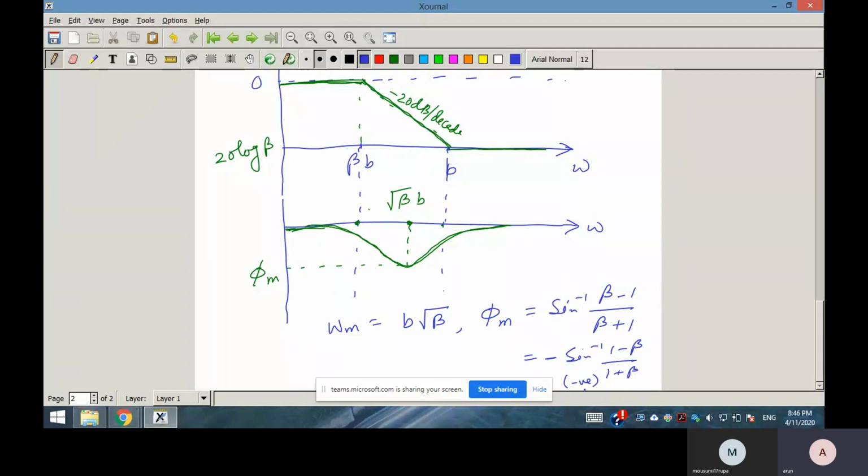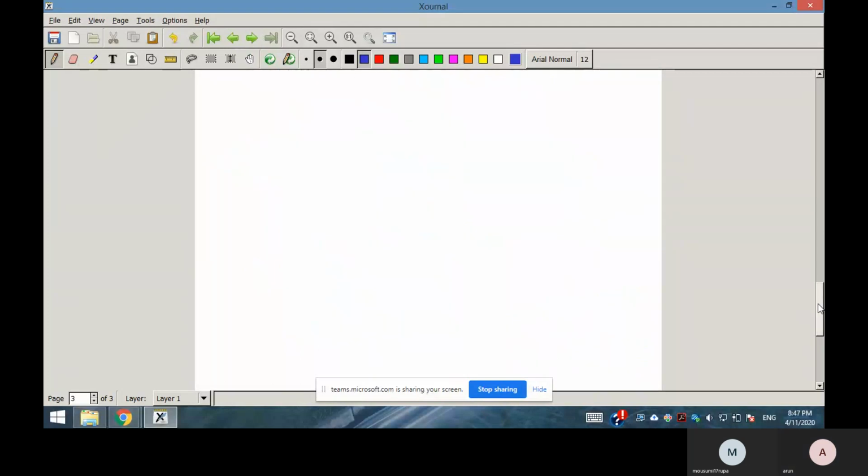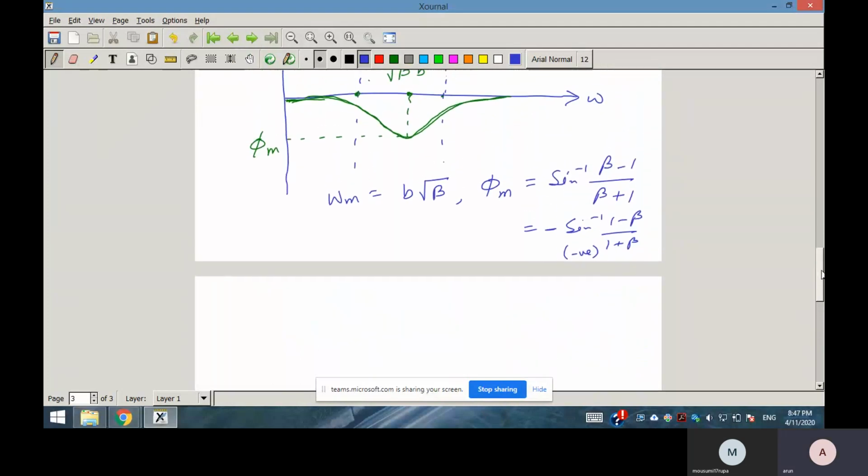Now how to design this lag controller using the algebraic approach, as we have done for lead controllers. This algebraic method is important, as I said earlier, that in most of the books they have followed some iterations, some assumptions, but here in one educational book he has provided a good algebraic method, so that I am following.